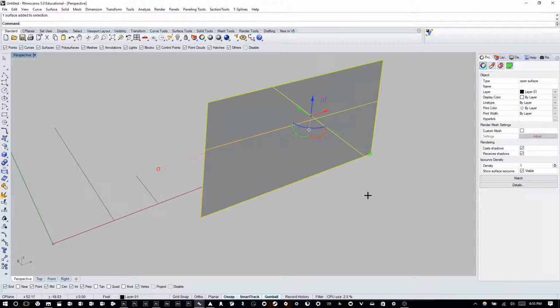So like I said, you can extract a curve from any point in that surface. And so oftentimes when you click on a surface, you'll see some of these lines here. These are called isocurves because they don't actually exist, but they're used to define the division or the quads of a surface. And you can actually manipulate those isocurves to get more divisions in that surface.